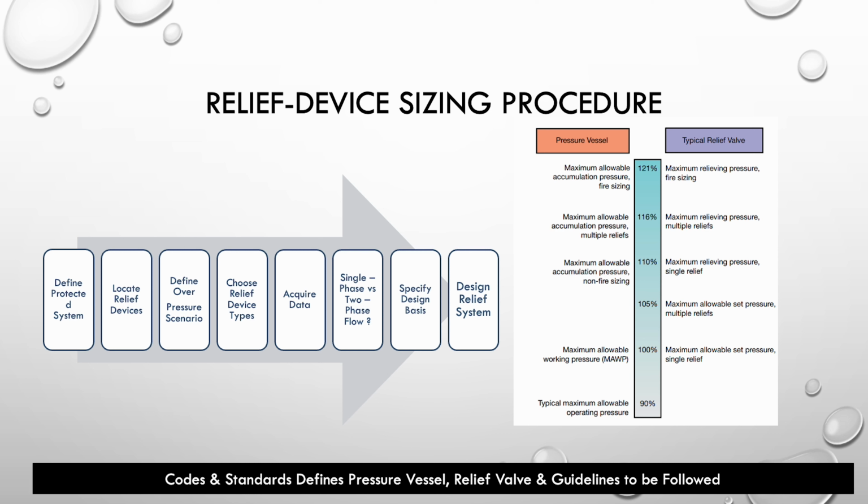You've got it. Where the relief valve is going to be installed, it's most likely is going to be on the piping if that piece of equipment is too small. Because just picture you're trying to put a relief valve on a pump. It's gonna be super hard in terms of fabricating it. But if you're talking about a reactor, for example, it's easier to do it because of the size of the tank. The same applies for an absorber or distillation tower.